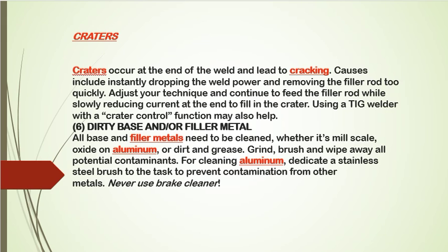Adjust your technique and continue to feed the filler rod while slowly reducing current at the end to fill in the crater. Continue to feed the filler metal while welding, and when you need to finish your welding, slowly reduce the current at the end. If you reduce the current slowly, it will fill in the crater. Using a TIG welder with a crater control function may also help. So this is how to control the crater.